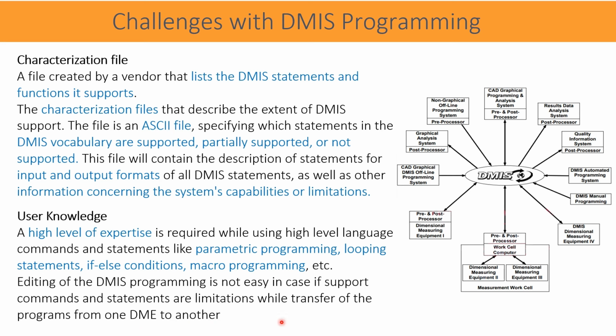When we transfer the program, it could be that the other DME, meaning the machine, has a different probing system or different alignment requirements. So sometimes the same command may not be available, and then the editing becomes a little challenging for the user. But a well trained, knowledgeable user overcomes all these obstacles and can make the program work.